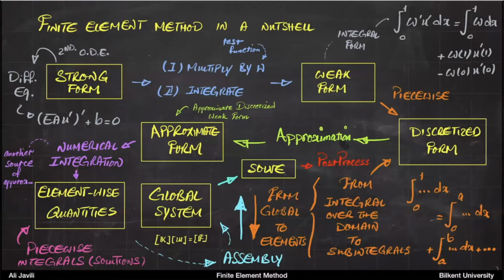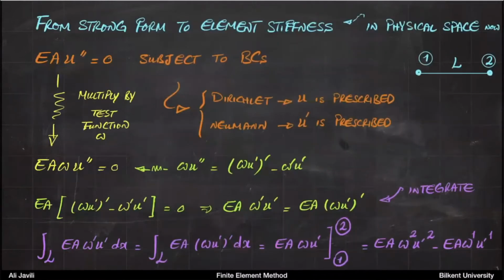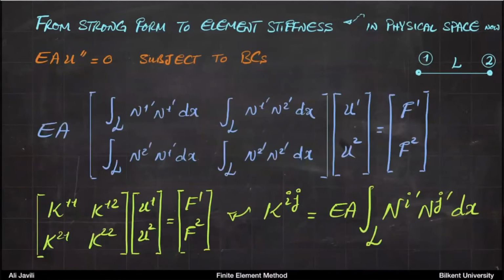This gives you the stiffness of each element. The only thing you need to do is to assemble the elements, and the assembly process alone, we have learned it before. So again, in a mathematical sense, this would be your strong form, and these are basically the key steps of the derivations that we have. We come to our stiffness as a function of x.